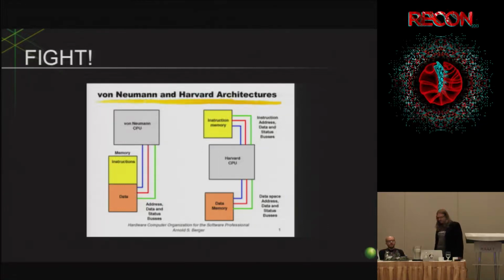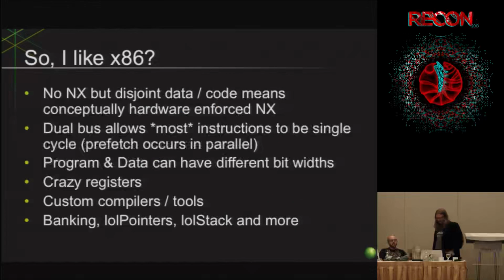But at least on the Tritium chips that we're going to be talking about today, it's very explicit. These are different spots physically inside the die on the SOC. As far as we can tell, we were never able to find any way to make them magically overlap. So you can only talk to one or the other, not both. You can never, for example, execute memory, because it makes no sense: the execution pointer only points to one particular spot, and there's no way to make it point somewhere else because these things don't overlap.